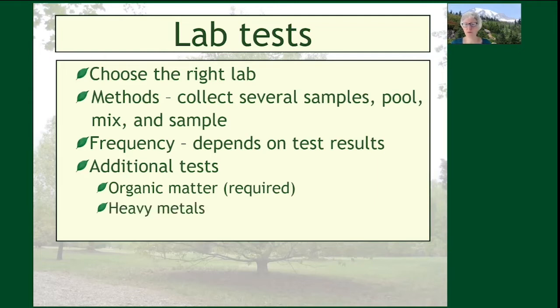If you happen to be someplace that heavy metals would be of concern, let's say you're doing restoration in a previously industrial site or something like that, if there's any possibility that there are heavy metals of concern for human health, you want to ask for those tests. And finally, if you happen to be in an arid part of the world where rainfall is pretty limited, or if you're in an area that you're concerned about de-icing salts, you'll also want to have a soluble salt test.